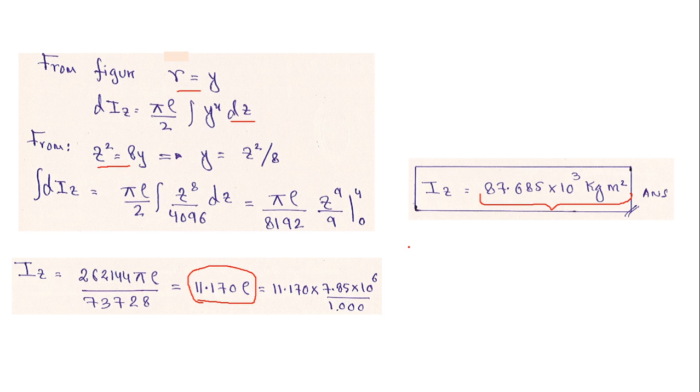So this is how you handle the problems of moment of inertia related with integration. Most of the time you always have to consider the disk element, because shell elements are only valid for cylindrical geometries that have non-varying formats along their length. For the rest of the cases you have to consider the disk element.